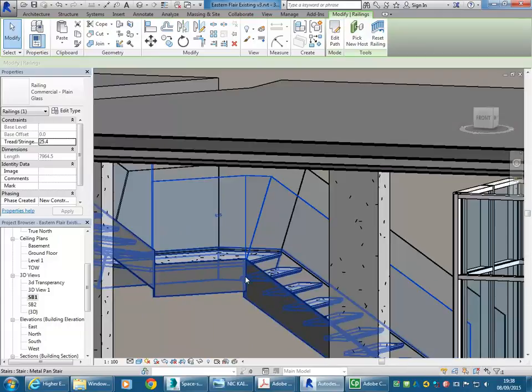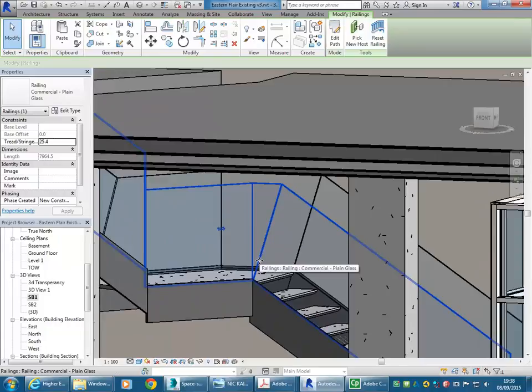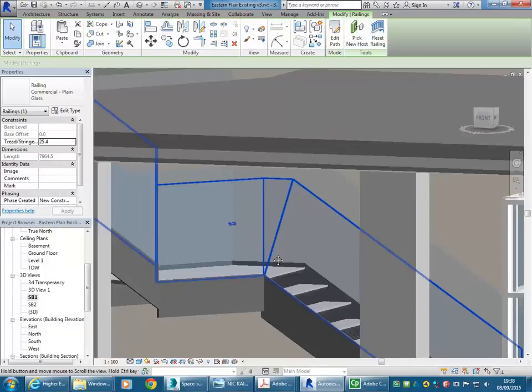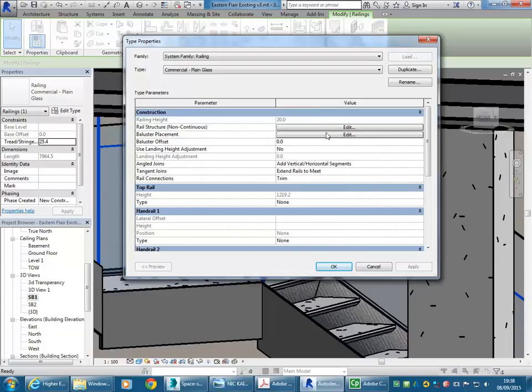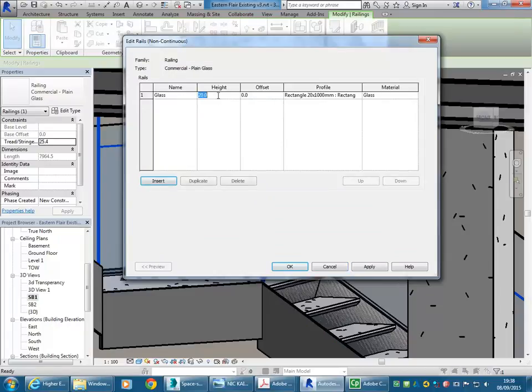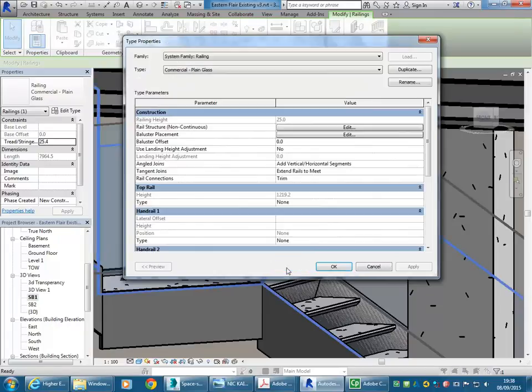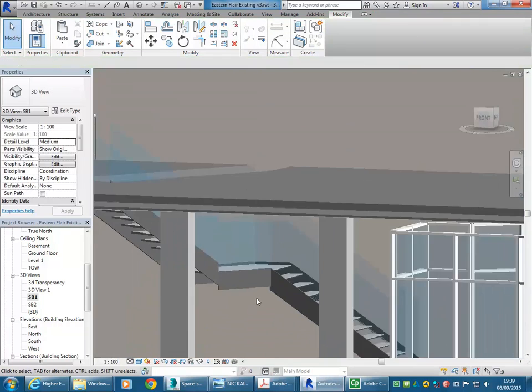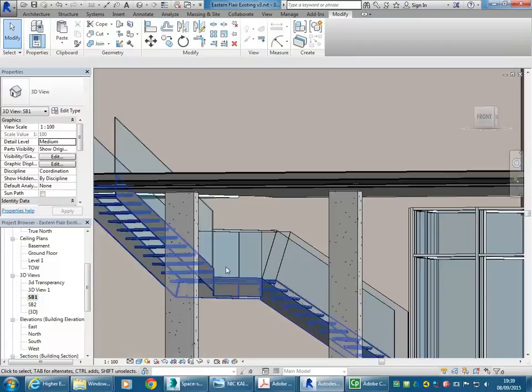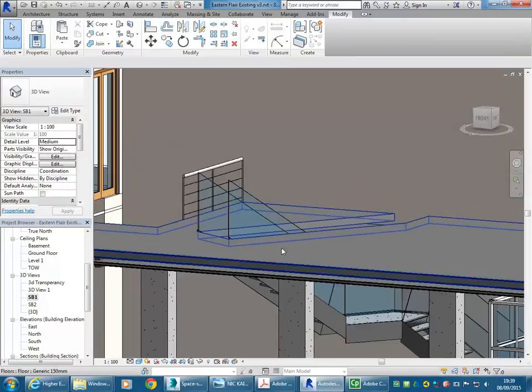So I think they should be more than a metre, personally. And also on tall buildings, when they've got them on the side of the building, it's again a bit hairy sometimes, and so nothing wrong with making them a bit higher. So with a bit of trial and error, you can get them to sit on top of your stringer. That's close enough, I think. And so you've got that railing for all the others that you want to do.